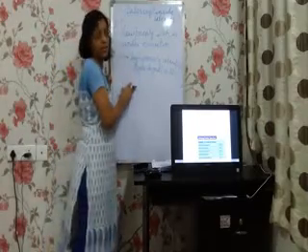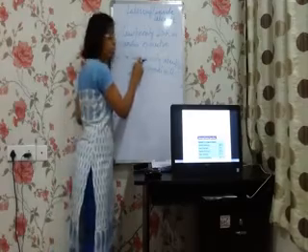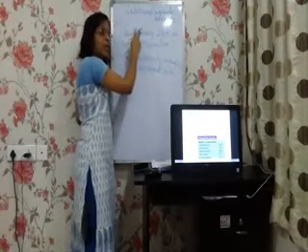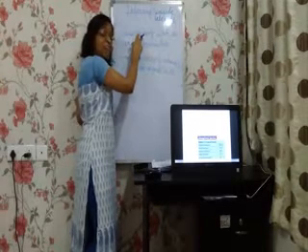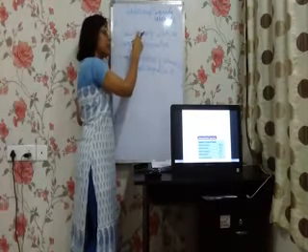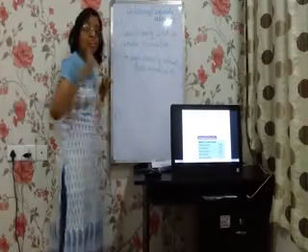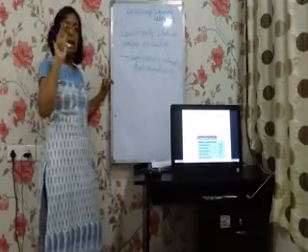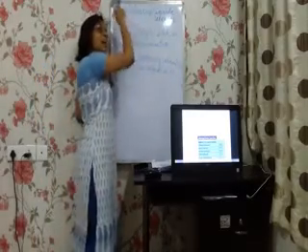So what will the microcontroller do? Because this interrupt has more priority as compared to the current one, the current ISR will be kept in a hold state. The microcontroller will branch from this ISR to the high priority ISR, serve that high priority interrupt, come back, serve the low priority interrupt, and then come back to the main program.